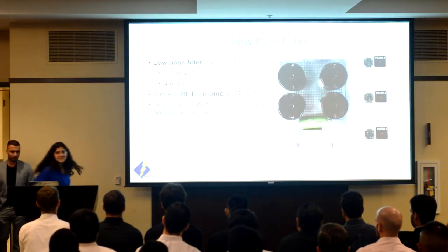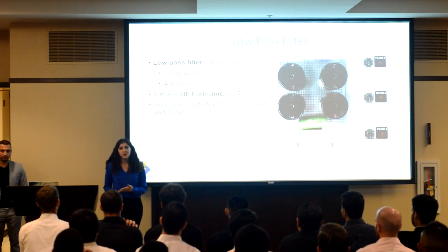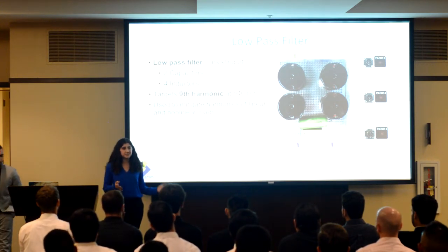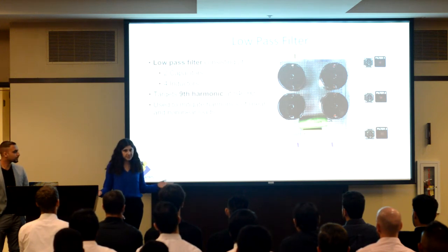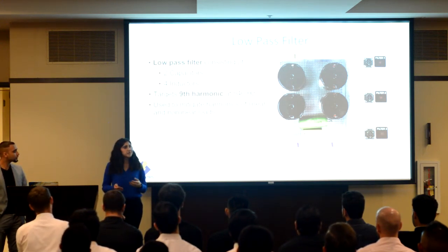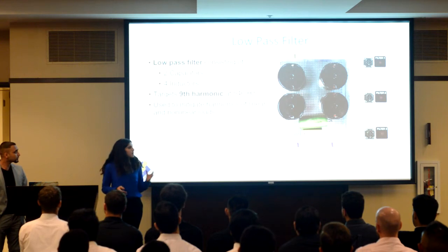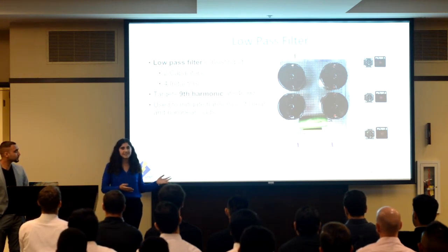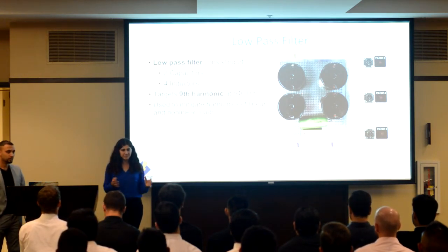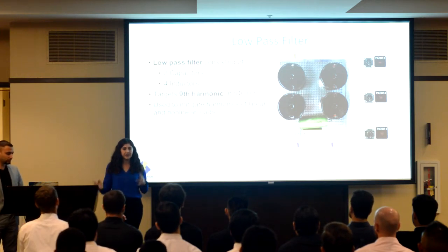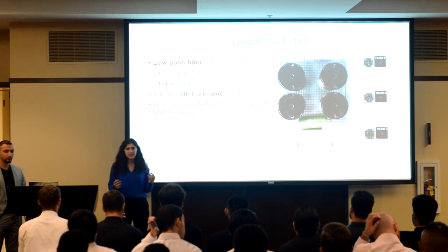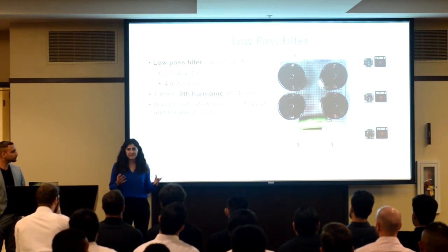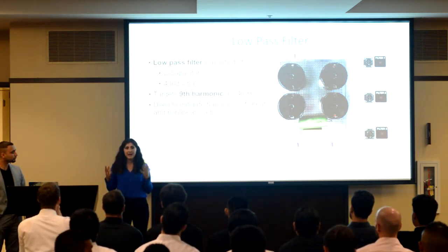All right, thank you, Ben. So I designed the filter for our overall system, and like many power systems, our model can facilitate the use of a filter. And why do you want to use filters? In the end, the use of a filter will reduce the amplitude of the harmonics that you saw on our previous slides. And by reducing the amplitude of these harmonics, you can reduce the total harmonic distortion in the overall system. And overall, you can expand the lifetime of some of your household items.